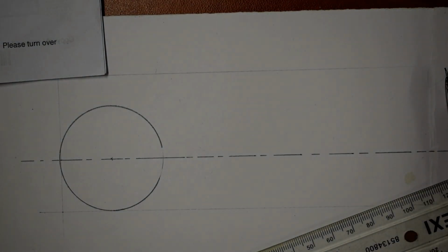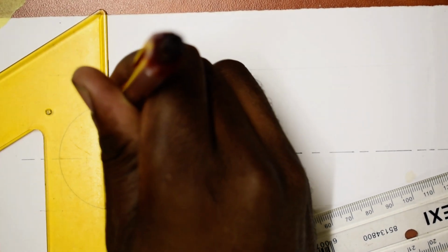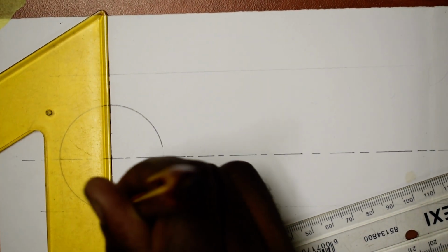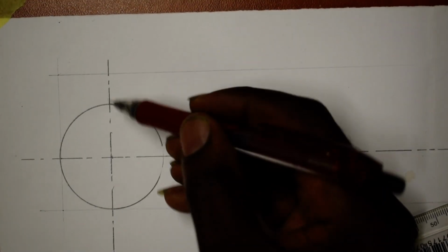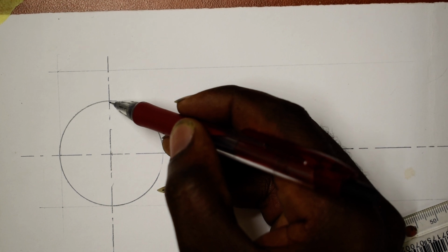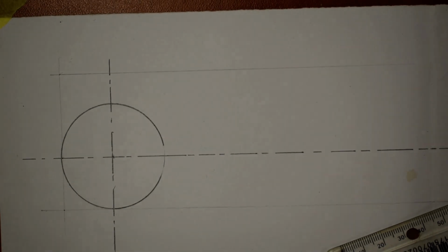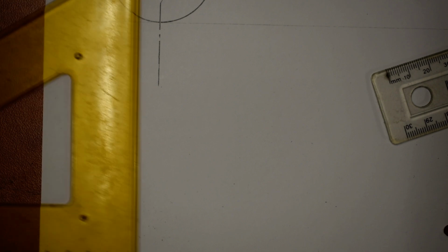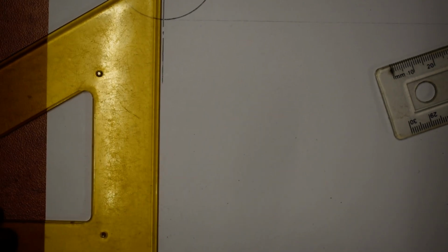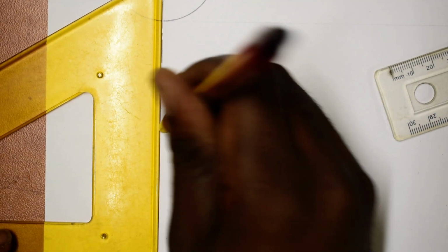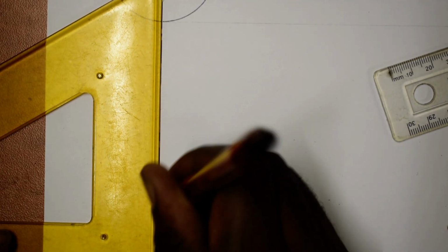So this side I want to draw it solid, this side just draw it a little bit faint. So where I was placing my drawing compass, I mark. I can put the vertical center line. Remember that your center lines must always overlap your drawing. So you cannot just draw a center line and be like you are ending here. It's not the right thing. So a center line must always exceed the drawing. So take it vertically down, so that it's also existing there by your top view, because you are going to need it.